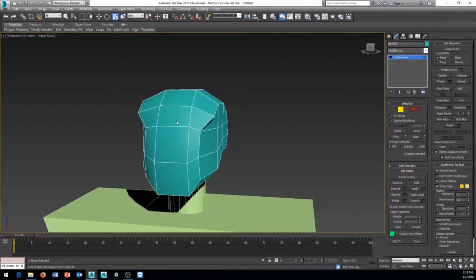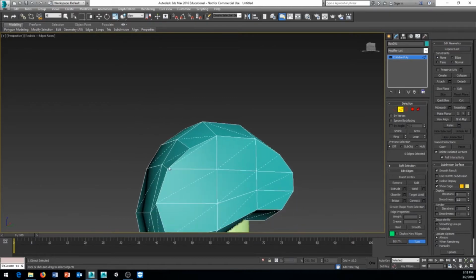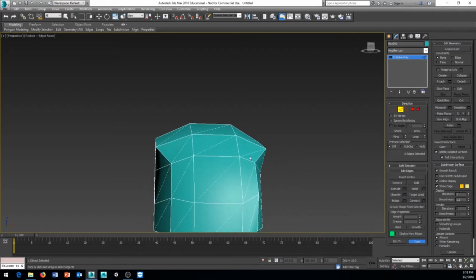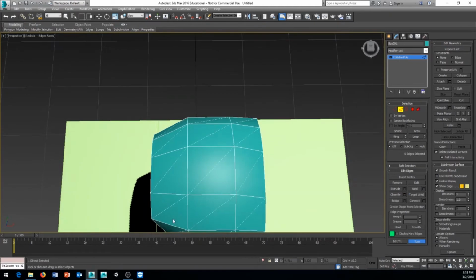And it's going to show all of these triangulated polygons. So now I can see how each polygon is made up of two triangles. And I see this edge right here. And now that I have it on turn, I can turn this edge this way. And now I match with what I had on the other side.